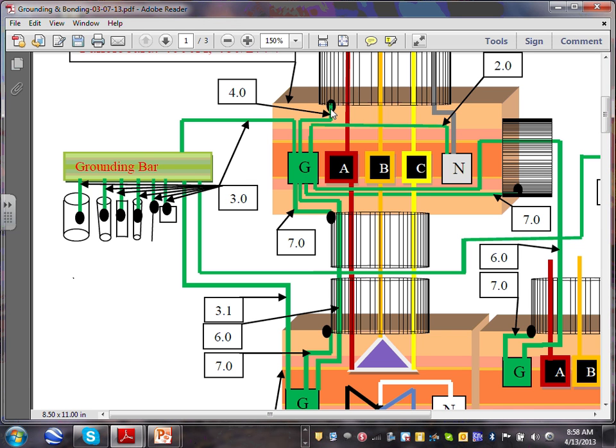So you have a 200 amp service, and you bring in an EMT conduit, say 2-inch, and the 2-inch matches. There are no knockouts, nothing, and you bring the EMT into the box. Then you can use a bonding wedge, or a connector that qualifies as a bonding connector. So there are multiple alternatives to the grounding bushing.